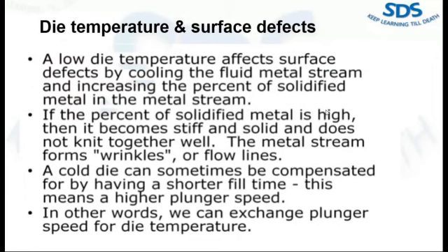Yes, I would suggest if you maintain your filling time in a close range, you should maintain your metal temperature within plus minus 5 degree centigrade range. What range? Plus minus 5 degree centigrade range. Is it not simple, as we are reducing casting weight just by reducing our wall thickness? Yes, we have to reduce 100 gram weight because some of the guys are also reducing and they are running successfully.